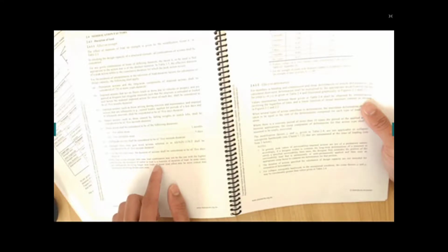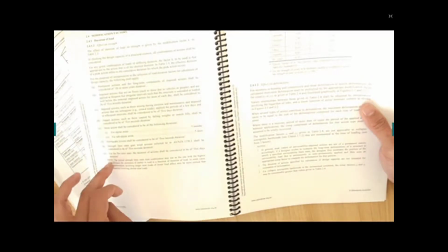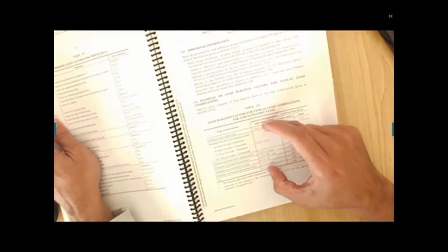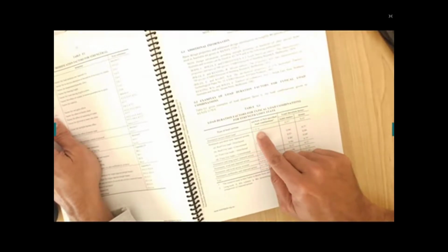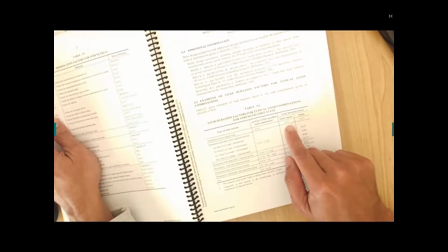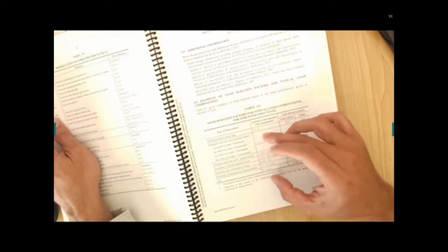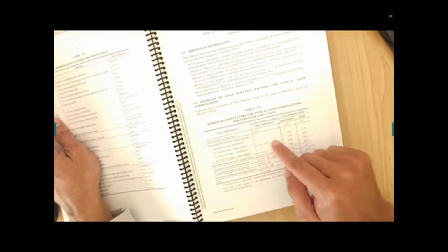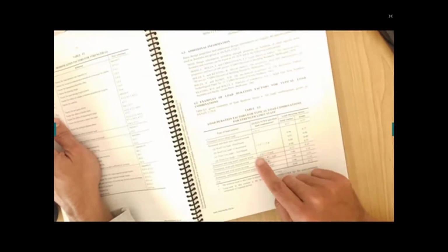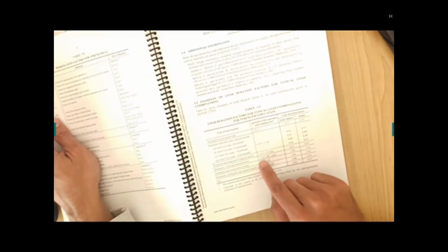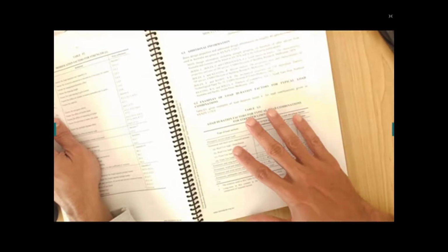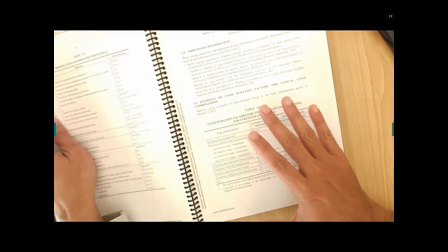Involving longer term load, lesser load effect. So what this note is saying is that you need to analyze all of these load cases. You need to do 1.35 G, and you do this one. You need to do this live load, and you don't know which load case would be the critical one. So you need to repeat the whole design for each of these, and you don't know which one is going to act critically.